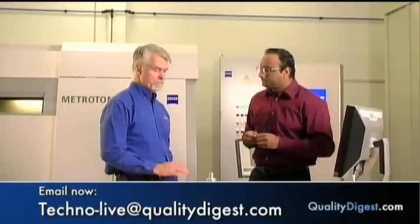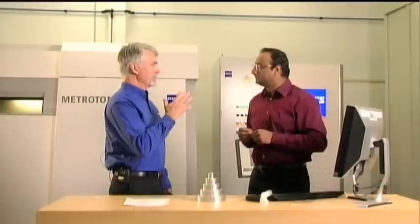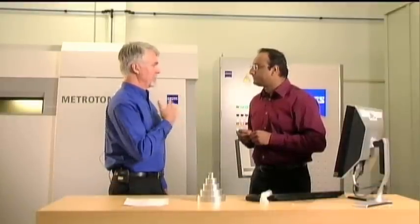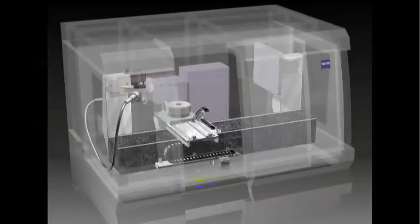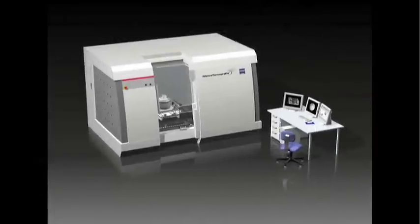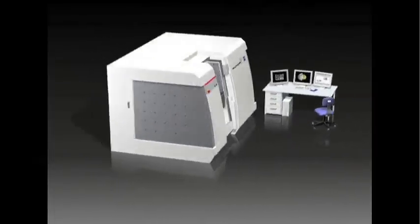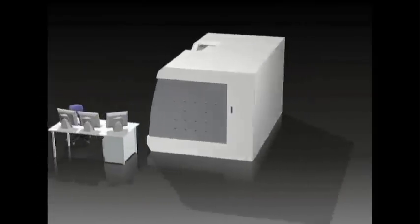Okay. Before we get further into this, run us through real quick basically how CT works. What is the principle behind it? Once I started a scan, I have a small video that shows what happens during the scanning. So if we can clip to that video. As you can see, a transparent view of the system. You have three major components inside the system: an X-ray tube, a rotary table, and the detector like you saw earlier.